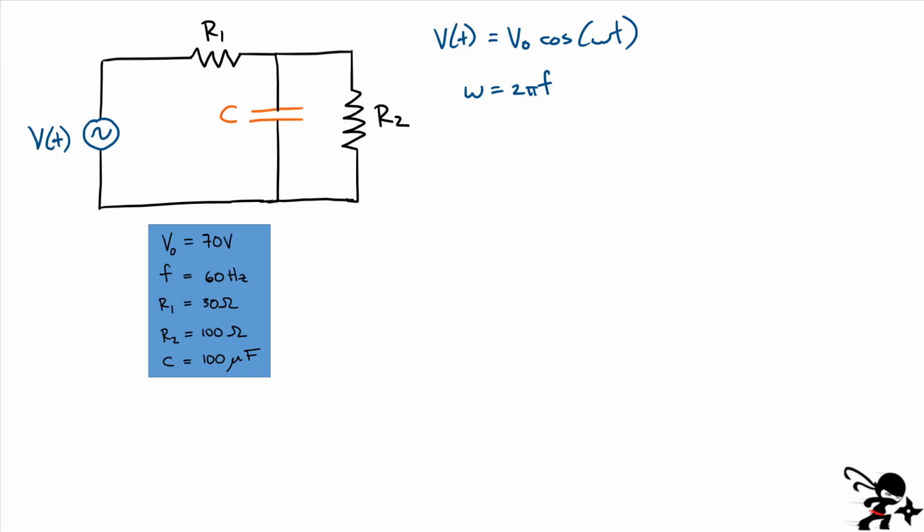The first thing you want to do whenever you've got a complicated looking circuit like this is, if you're able to simplify it in any way, I think you should start by doing that. One thing we could do is keep this AC supply, and then try to simplify this network of resistors and capacitors and replace all of that with just one single total impedance value. So we have to combine things that are in series and parallel in order to get to this Z total value. That's going to be the goal.